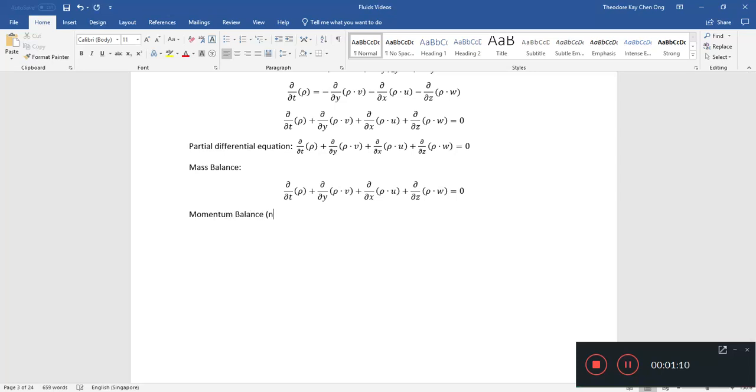Now these are what Navier Stokes are actually about. We have to perform that over the same box that we were talking about earlier. In a textbook, you'll probably see that the Navier Stokes equation only refers to this momentum balance, but I like to lump these two together. It's easier to remember that way, because you don't have momentum balance without mass balance.